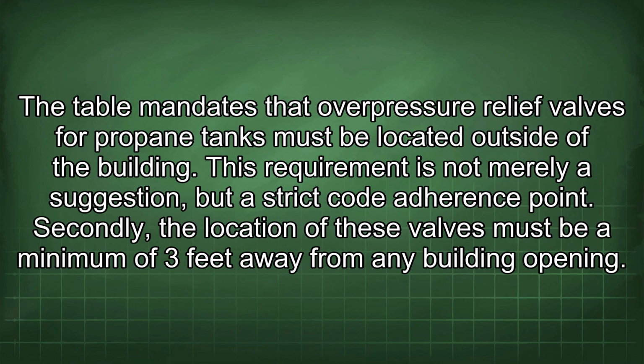The table mandates that overpressure relief valves for propane tanks must be located outside of the building. This requirement is not merely a suggestion, but a strict code adherence point. Secondly, the location of these valves must be a minimum of 3 feet away from any building opening.